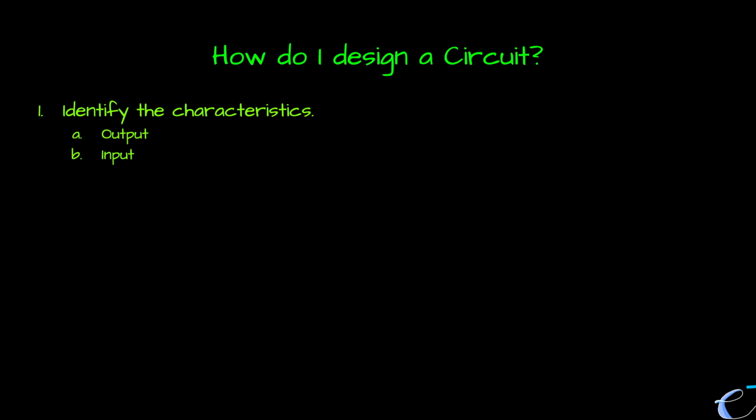However, there are many other considerations that you will need to make to have a successful circuit. Things like cost, availability of components, power consumption and efficiency, and the form factor of the circuit. Is a breadboard good enough? A breadboard might not be a good solution for a circuit that's going to be used for the long term. It cannot be a permanent solution, for example.